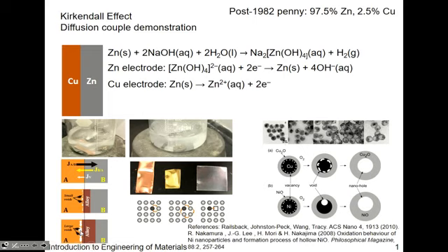And that, of course, has implications in terms of mechanical properties. If you have a lot of voids, if you have a lot of defects, this is what you get, right? You just get a bigger void. And generally, that's not so great, unless you're intending for that. So if you're intending to make these core-shell type structures and taking advantage of the Kirkendall effect, you can create structures that are hollow like this if you just wait long enough. So recently there was a fabulous publication where they put nickel and platinum together, and people do this a lot to reduce the use of platinum. So they put in a base metal, some inexpensive, abundant metal.